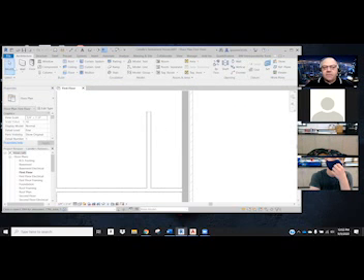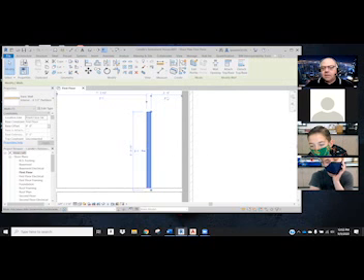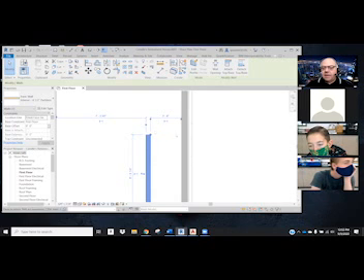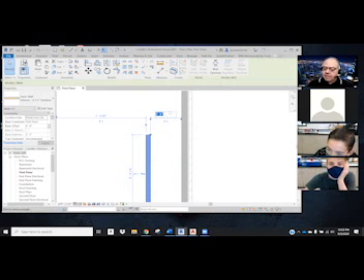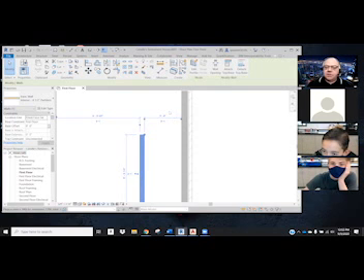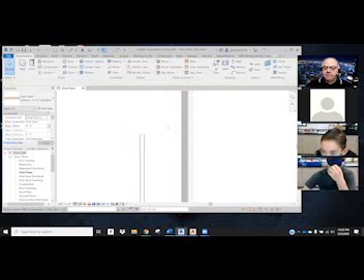If you go to your modify window, your little button here that modifies on the fly, if I select this wall, there's a temporary dimension that's giving me that value. So if I go ahead and just click in that box, I can tell it I want 3 feet and enter, and it will shift that wall for me. So it puts it where it's supposed to be.